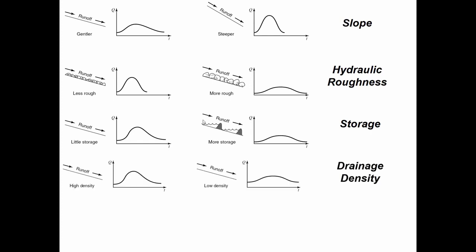All right. So drainage density is where we're talking about there being a lot of streams draining a network, a watershed. So if I draw a little watershed here, a low drainage density would be just a main channel and maybe a couple of branches. And so if we have a low drainage density, then it's going to take longer for all of the water to make its way towards the outlet, because this raindrop has to flow over land, which is slow, before it finally gets into this high-speed network that it can travel through more rapidly.